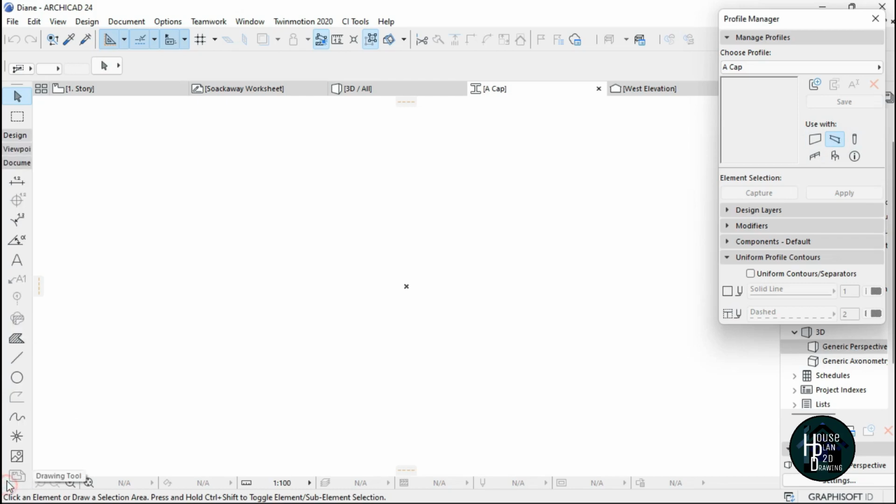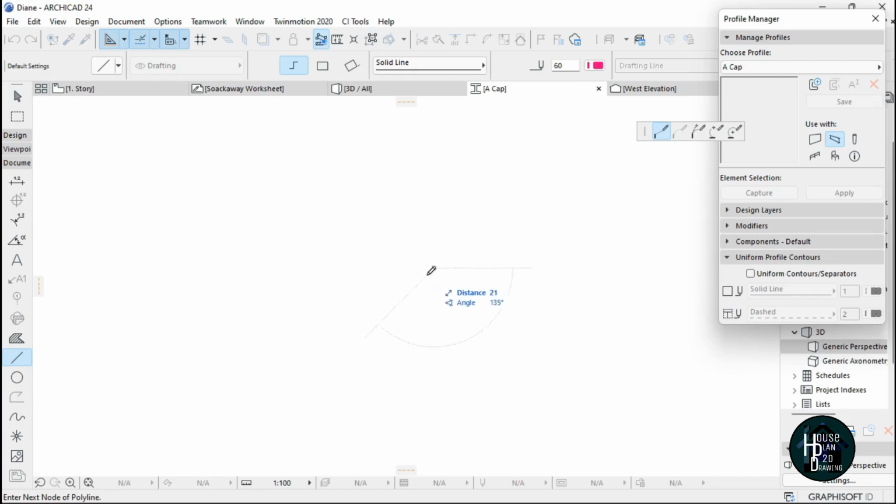Click on OK and click this beam to untick this. Now go to document, click on the line tool, and I'm going to click from this X here and stretch it to this other side here and give a dimension of 225. Click enter twice. I'm going to raise this up by 50. Then I'm going to hold down shift, click this X here, then click again, and pick another line from this X, move it to this edge here, and give it 50. Click enter, take it up.